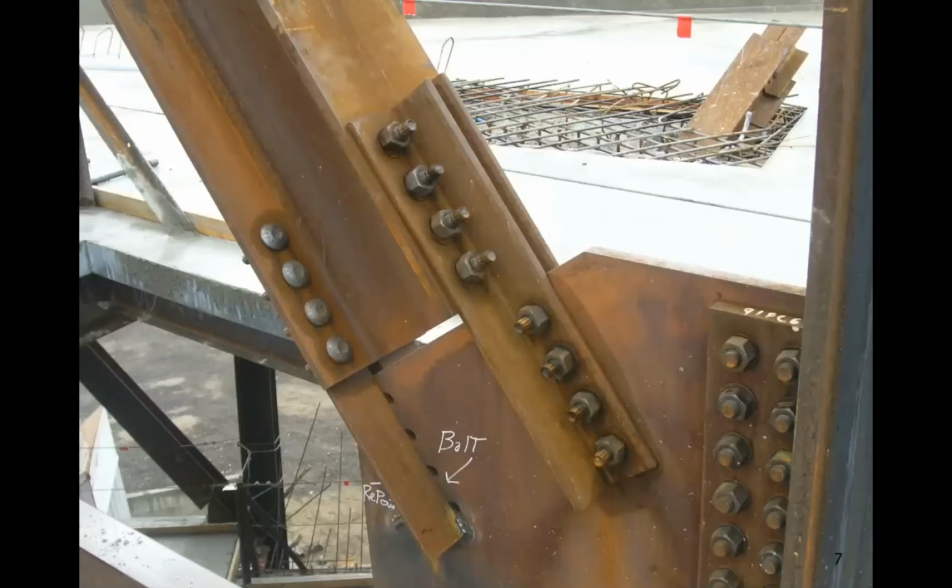For buildings with really, really heavy loads, we might even resort to using a W section. Normally, W sections have significant areas. There's a lot of steel in these. You can fit a lot more steel into bigger W sections, and so the kinds of sections available on the market to use as braces or columns, we tend to have very heavy sections that we can roll using wide flange sections, and so this would be a very heavy brace that's expected to carry lots of load.